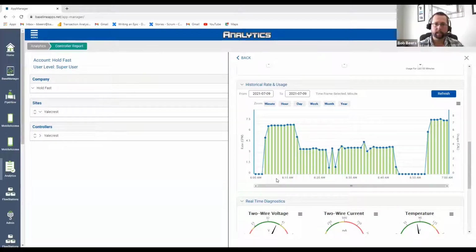Yeah, and looking at the data, different data points, different data types, and then how you use that information and who needs it and when do they need it, and being able to look at things like this. It could be the end of program 1 and the start of program 2, but you've got a little gap here. You can see it at the controller level, and this could help inform programming methodologies to tighten up your water window if you're not using things, say, like managed by flow or other unique baseline features.